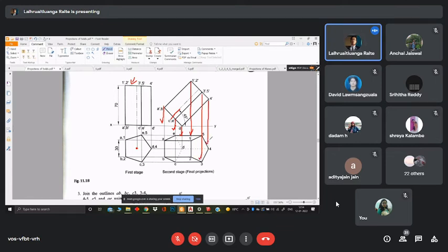Okay. All right. Now that we get all our points, when we join them, we must do our visualization again in order to not mess up the lines which are hidden and the lines which are not. Now remember, when we tilt it like this, this face is going to be very much visible, right? Because we are going to tilt it this way and it's going to be open. So A1 to B is visible, and the whole profile of this is also going to be visible on the top side, 1, 2, 3, 4, 5. The numeric part is always on the top side, so it's visible.